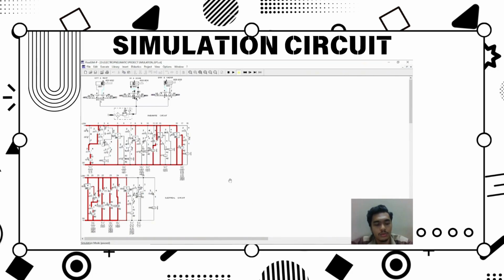After timer -T2 counts for 3 seconds, timer contact -T2 will close and energize coil relay -KF8, and relay contact -KF8 will open and deactivate solenoid coil -MB3, and relay contact -KF8 will close and activate the solenoid coil -MB4, and then activate right switching position and allow air to flow from port 1 to port 2 at the piston rod -MM2 will fully discharge position for double acting cylinder DSC.